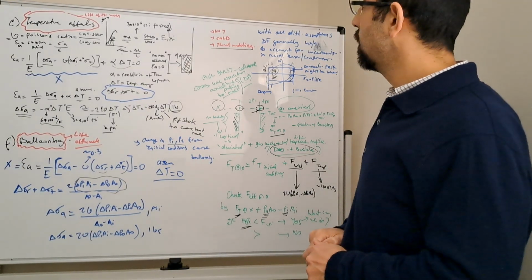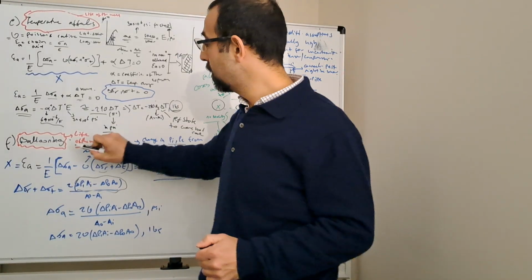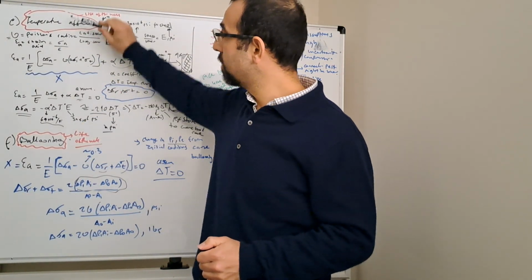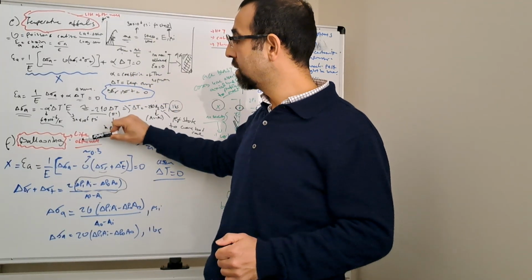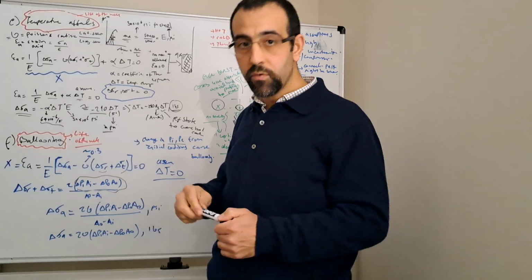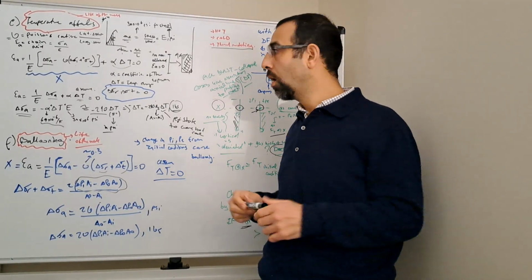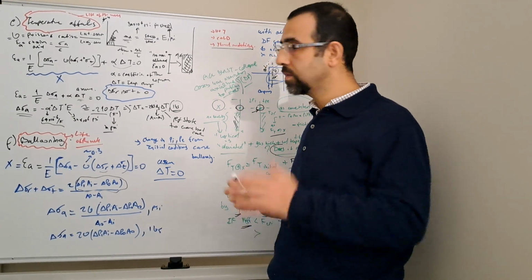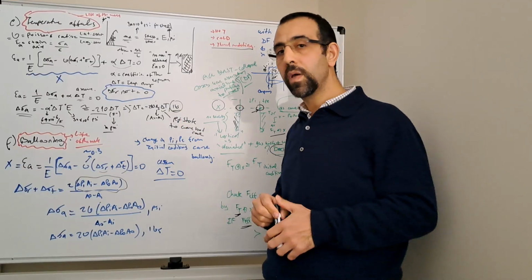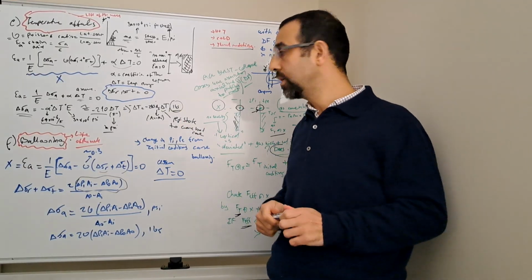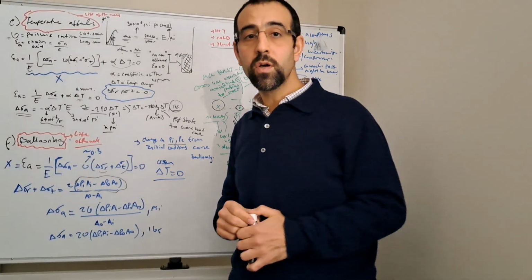I think we covered it all, and again, temperature effects and ballooning impact the life of the well, from running the completion to production and all the associated cases, because when you bring the completion fluid inside, it heats up and tends to heat up the neighboring casings behind it. Okay, thank you very much. See you in the next video.